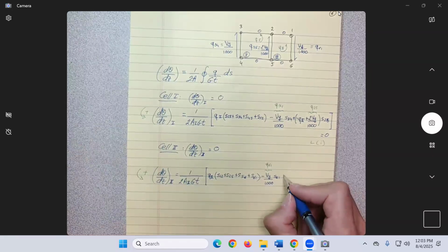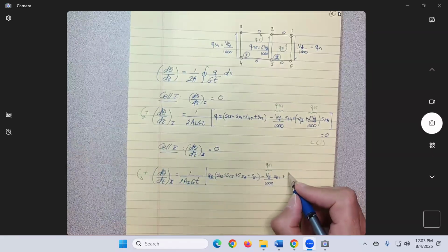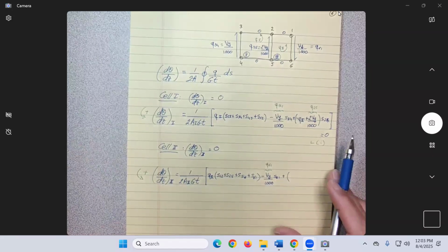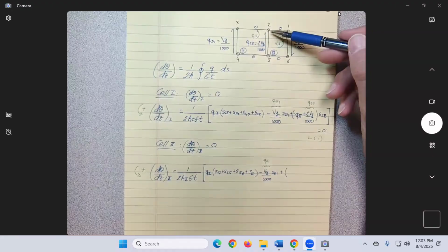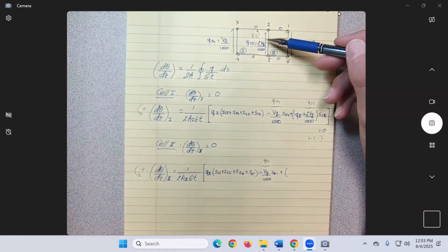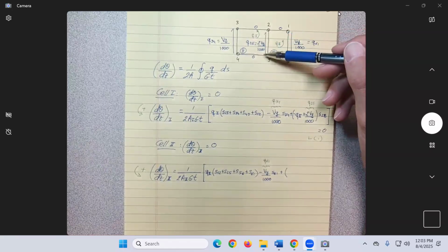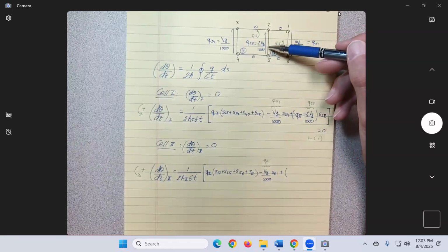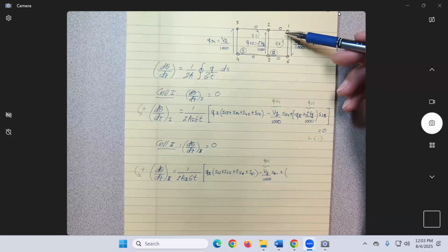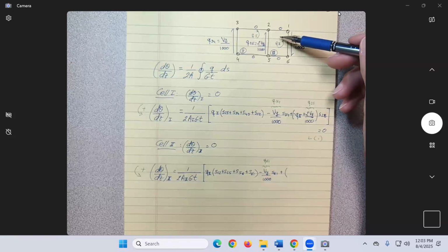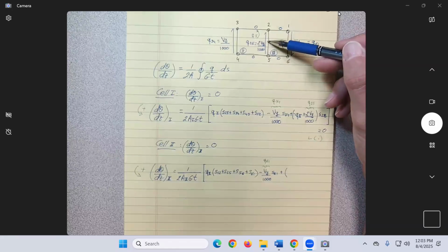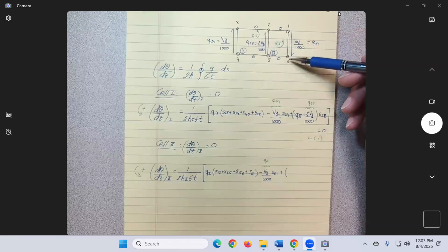And now we'll do the same thing as before. Now I'm going to do whatever is on top of 25. So on 25, we have Q1. So Q1 goes up. Is it going to make cell 2 go clockwise or counterclockwise? It's going to make it go clockwise. Q1 coming up here will make this bend clockwise.